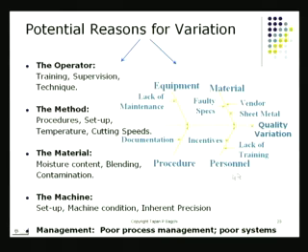And here's another way to present the same thing. If you recognize the tool, it is the fishbone or the cause and effect diagram. And quality variations would be there when there is lack of maintenance, faulty specifications, the vendor has some problems there, or the sheet metal that is being used, it's got some problem there. Personnel might be also causing variation because the incentives are not good enough, lack of training is there, and the procedure is there, but there is no documentation. So each person uses the procedure in accordance to his own understanding. These are the variety of different factors that can lead to the chart fluctuating.